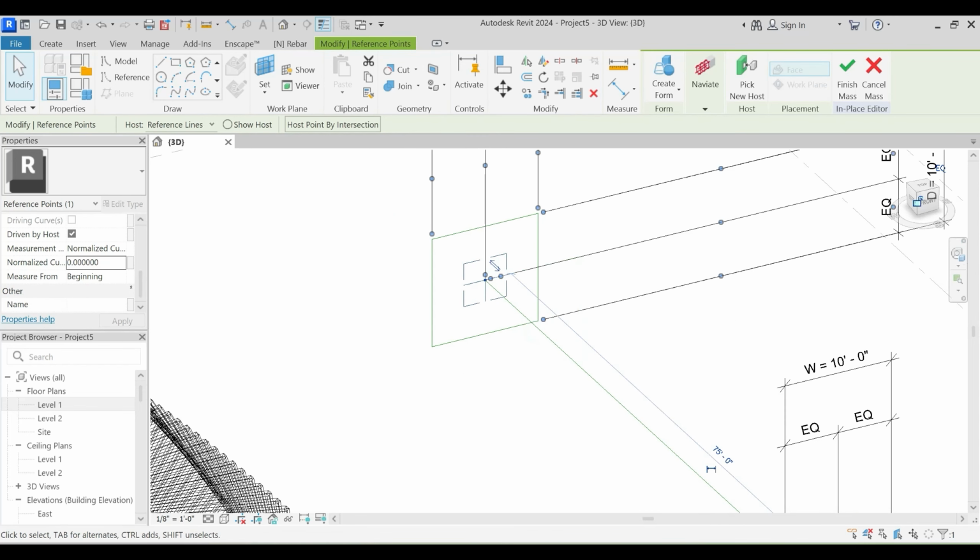Okay. So I'll just click undo and select this point and associate a family parameter to this, calling it R for radius, and that could be an instance. Okay. And with that, I'll just say that okay. Fine. I'll just go to this particular family types and change this R, this rotation angle, to 90. Okay. And just apply and okay. Okay. So with that, you see that we have achieved that particular form. The fundamentals and basics of this particular form we have achieved.